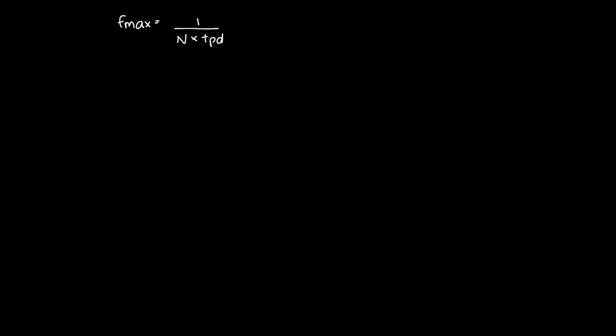Now, the second problem I saw was those weird timing glitches in the timing diagram, and those were caused by the asynchronous reset. So I only see those glitches when I have an asynchronous reset, which occurs when I have a non-natural mod number. Recall that a non-natural mod number is a mod number that is not equal to 2 to the n.